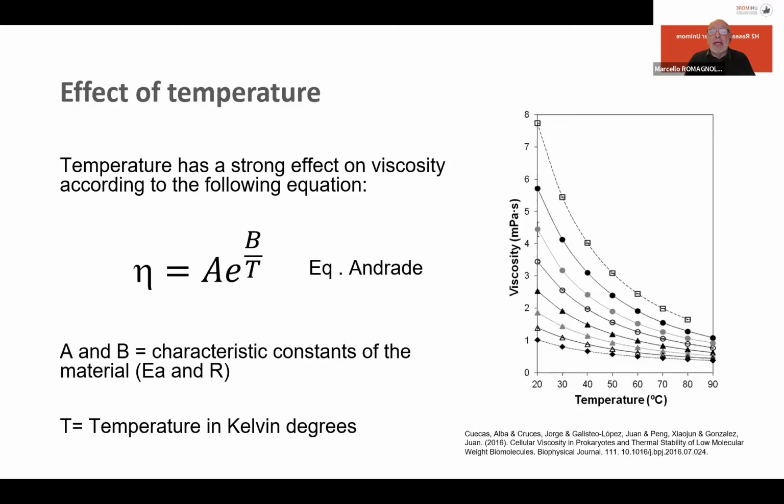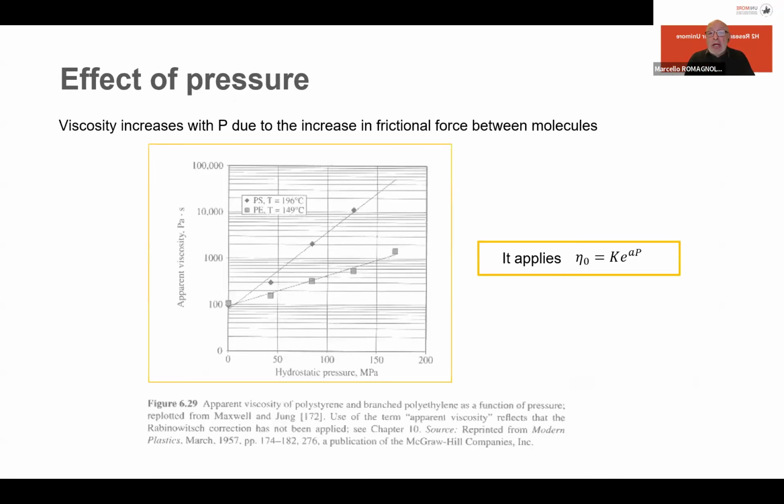And so we could also see a change of the rheological behavior. That means also an increase, for example, of viscosity, because we have a solubilization of the salt and the degradation of the polymer additives that we have introduced. So the effect of the temperature is not in one direction, but it can be also in different directions.